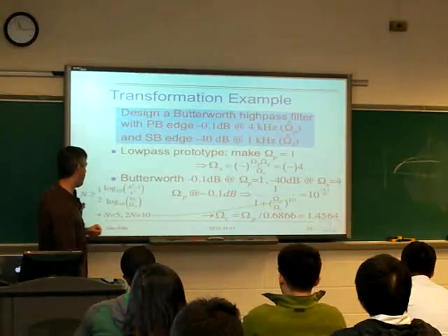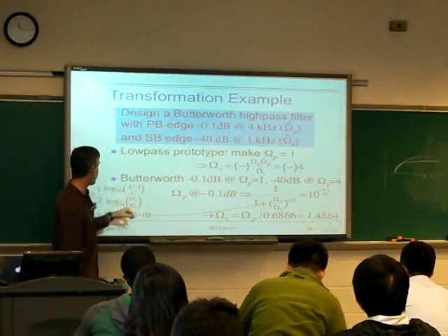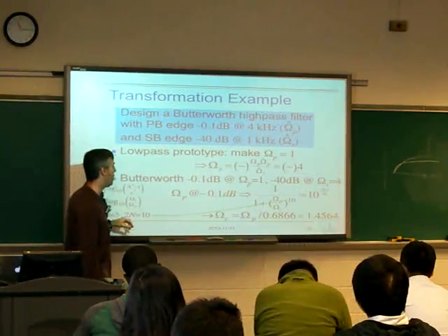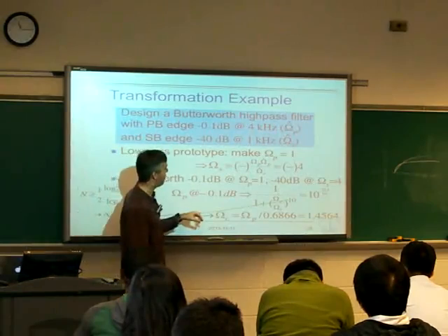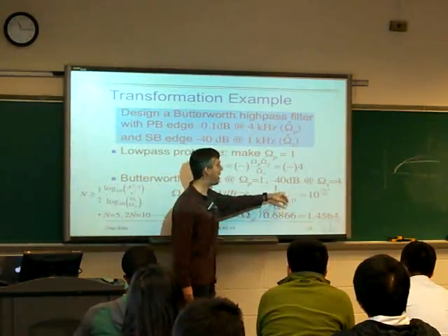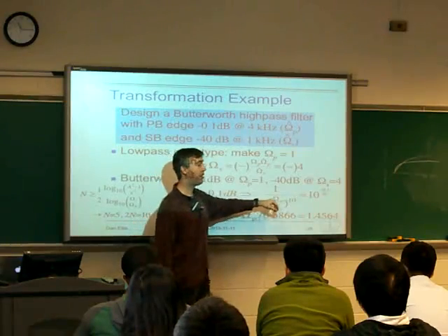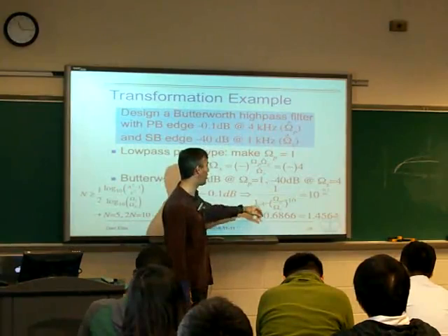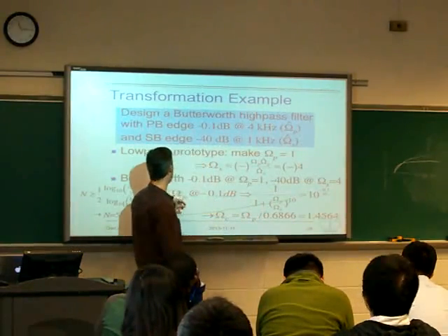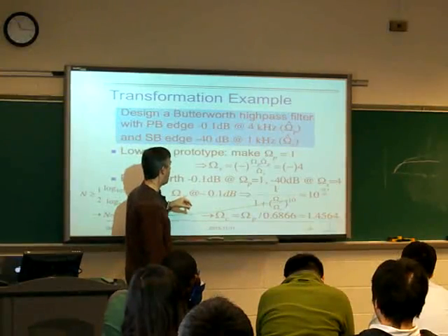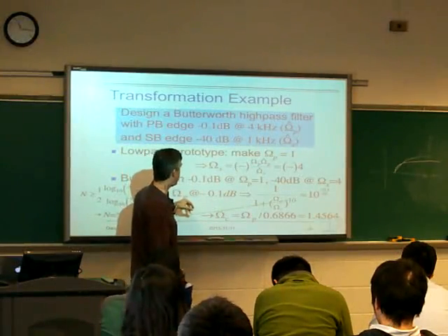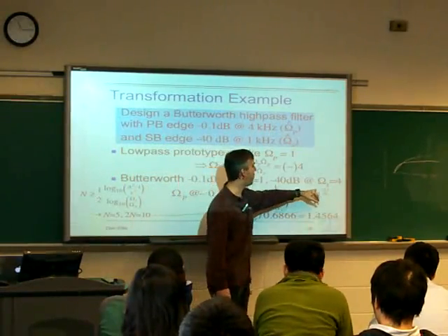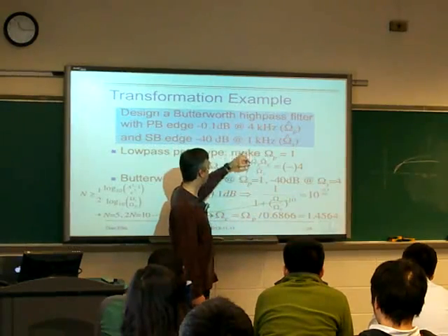So we have these specifications. We can plug them in. Here we get that the order has to be 5, which means that we can then plug that into our Butterworth magnitude of H of s squared function to solve for the appropriate passband edge that will give us this thing being 1.1 dB down at 1 kilohertz.